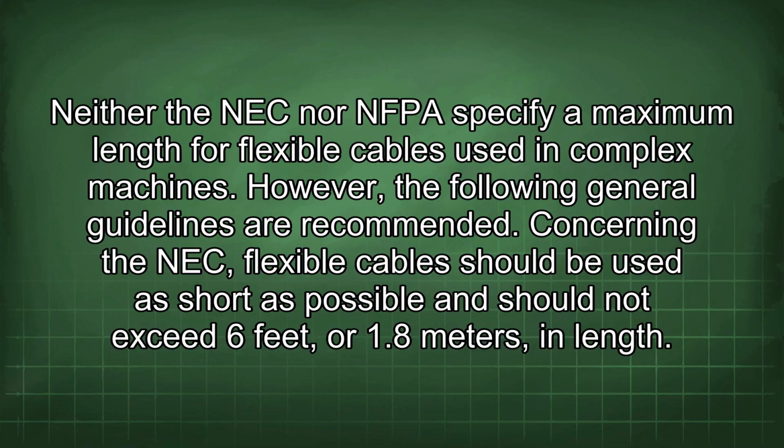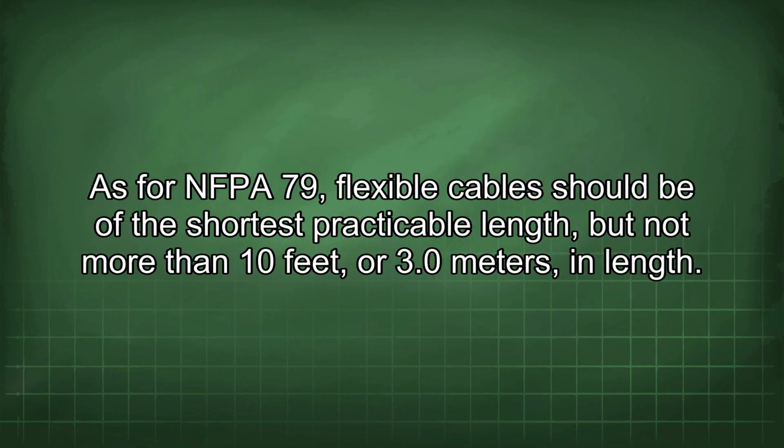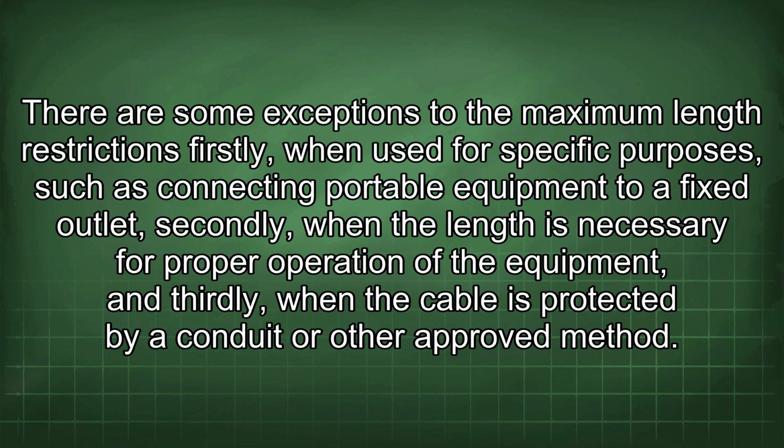Concerning the NEC, flexible cables should be used as short as possible and should not exceed 6 feet or 1.8 meters in length. As for NFPA 79, flexible cables should be of the shortest practicable length, but not more than 10 feet or 3.0 meters in length. There are some exceptions to the maximum length restrictions.